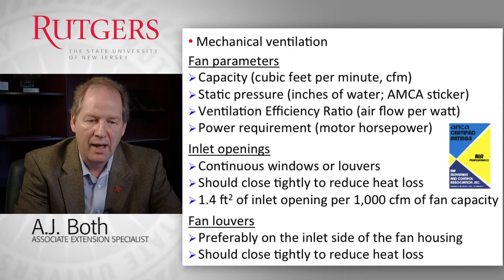And typically fans are rated by an independent testing laboratory based on a set of guidelines that was developed by AMCA. And when fans are rated like that and checked and confirmed that indeed at a certain static pressure they were able to provide a certain flow rate or capacity, then they get a sticker indicating that they passed the test. So when you think about buying fans for greenhouse ventilation applications, you want to make sure you buy a fan that was tested properly, and the result of that test are indicated by the AMCA sticker that you will find on the fan when you purchase it.